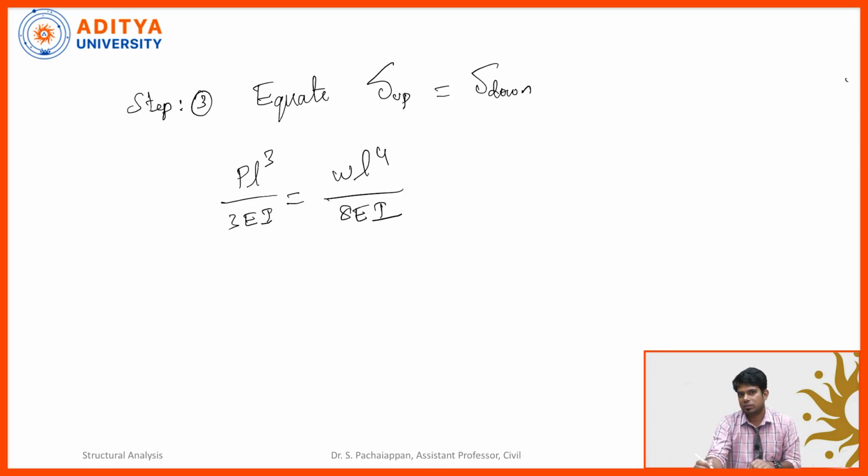In the examination, in order to confuse you, they are going to give you the values of E and I, and they might give them in different units also. Please don't convert that unit and substitute the value, because anyhow EI will be cancelled while calculating the prop reaction. Afterwards, nowhere are we going to use that EI value. There is more possibility you can commit mistakes in converting the units. So here we need not substitute the value. Don't substitute the EI value.